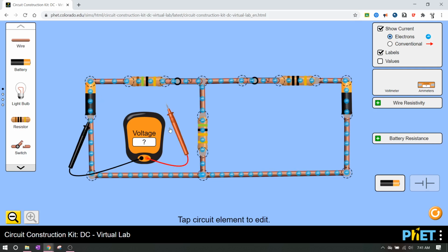All right, so let's see here. The current meter is a little bit different, because it's got to have junctions put up to it, which means you're going to have to add this as part of the circuit. If you want to break junctions, you can click on the little scissors on the junction, and it'll break them up. You can add the current box in between the 2, and it will tell you what the current is going through that circuit, which is really handy. It's not going to come out perfect, but I can actually see that there's a current of 0.5 amps going through this particular circuit, and there is a voltage of something or another going through there. Anyway, you got to have both